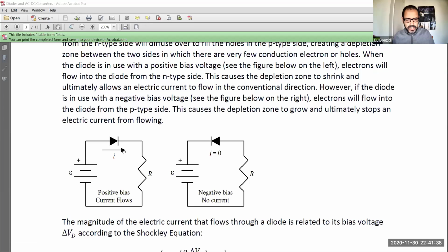in this case, I'm connecting it to a battery. You need the resistor always, because if you do it this way, it's going to have tremendous current flowing. It's going to burn it. So usually for safety, you always have to have a resistor in there, okay? You really have to follow the directions when you're doing these things. Otherwise, you'll have a problem. So there will be a current in here, and that current will be more or less, I mean, slightly off, the EMF divided by R, okay?